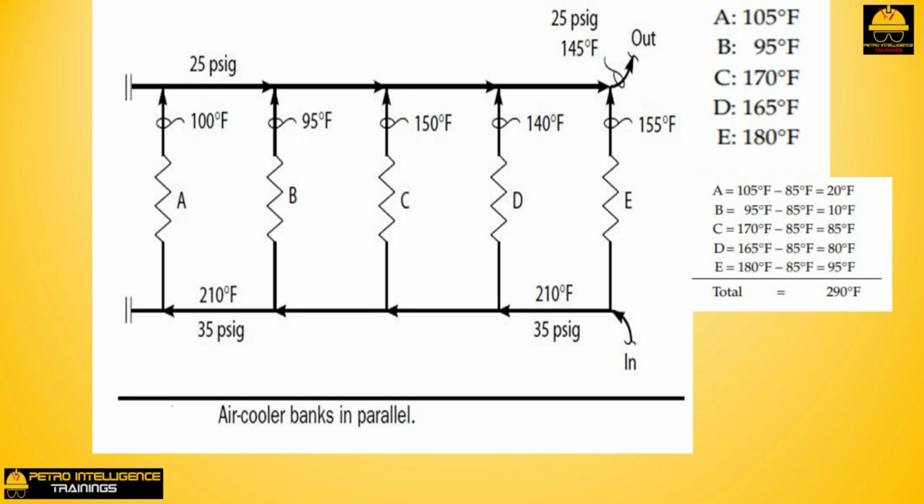It is not all that difficult to decide whether the airflow through identical coolers is similar. I just wave a handkerchief in the breeze at a few spots above the cooler.